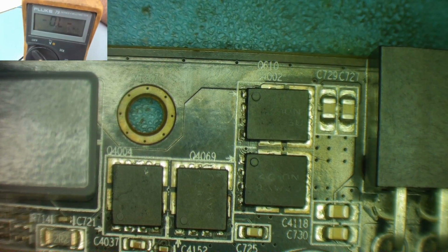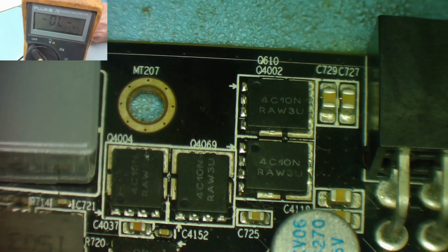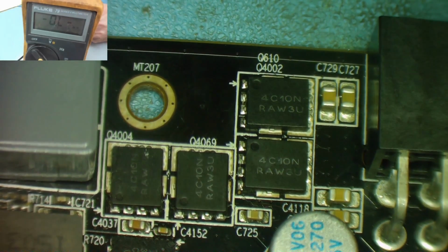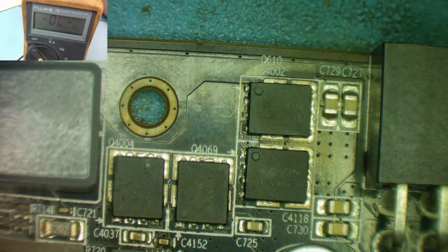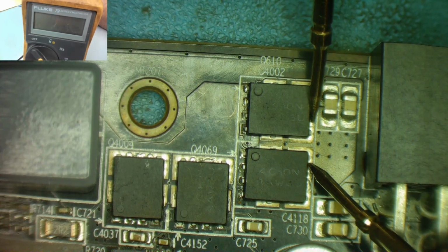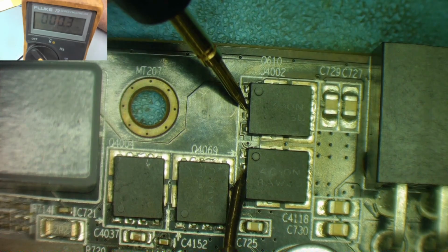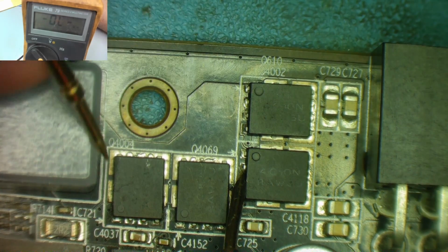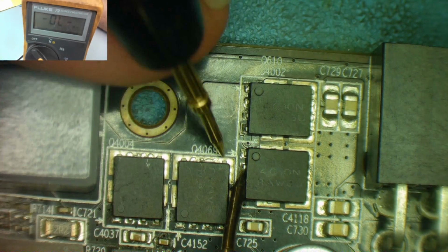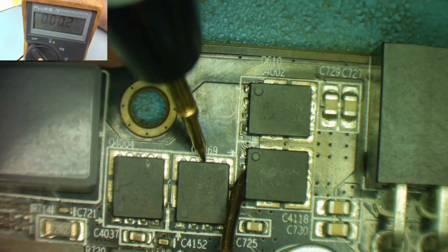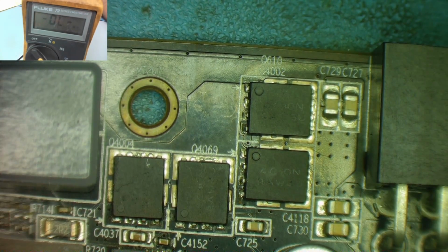And if we take a closer look at this one, just to prove the rule of thumb I've just told you is not always correct, this has 4 MOSFETs, 4C10N. And if we look quickly, you'll see that the top 2 are connected in parallel. So these are one side of them, and this is the other side, drain and source. This is the source, and they're connected together. And then the source of these 2 will go to the drain of these 2. In fact, I'm sure you can see the large circuit trace that comes down here. Okay, and then the other 2 ends will connect to each other as well. So we have 2 pairs in parallel.